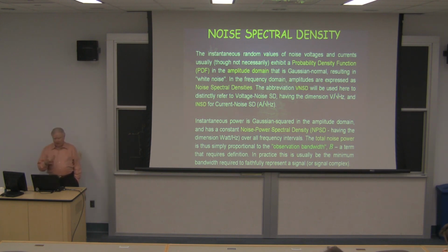So in talking about noise, we'll talk about NSD, noise spectral density, or voltage noise density. And that has a dimension of volts per root hertz, excuse me, I almost lost my root sign. And similarly for current, of course, it's so many amps per root hertz.